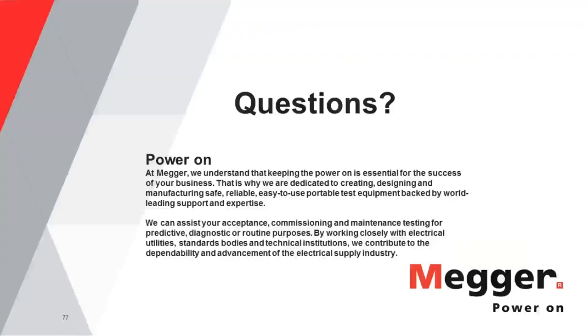Okay, thank you, Jamie. Well, the very first criteria is to always check with the manufacturer specs and see what the recommended practices are by the manufacturer. If you don't have access to that, there are other sources to determine the correct voltage to be applied. One of these sources is the NETA table 100.1, which is a very useful table.